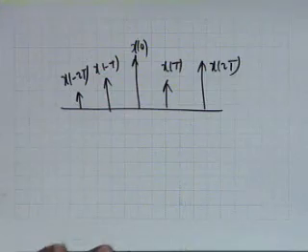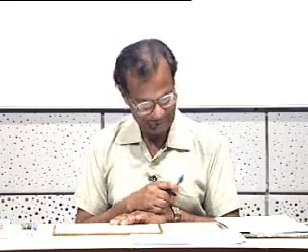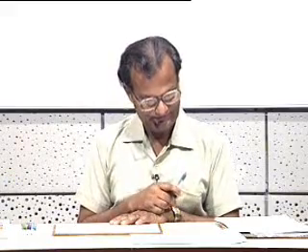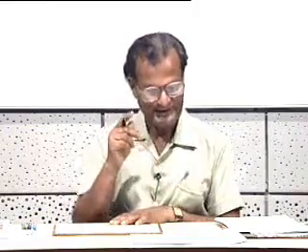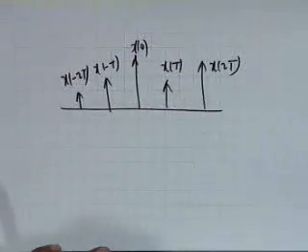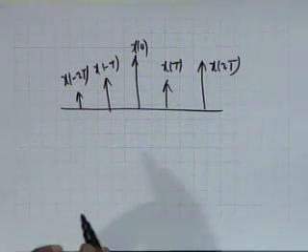But the Fourier transform is always unique for a given function. If we take two different signals whose sampled version is the same, we'll get two different spectrums, and both of them correspond to the spectrum of the sampled version. Well, this is the essence. If we have a signal whose samples are these, the signal is not necessarily unique. We can have two signals, as we illustrated last time, having the same sampled version.